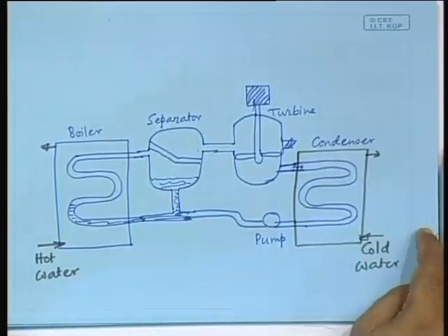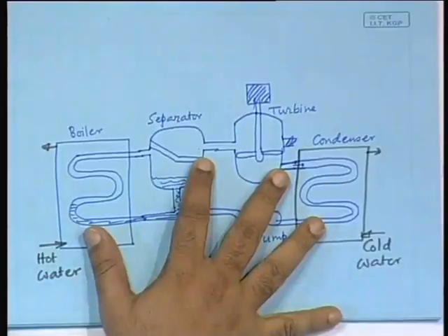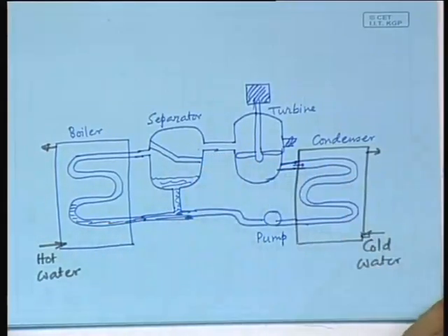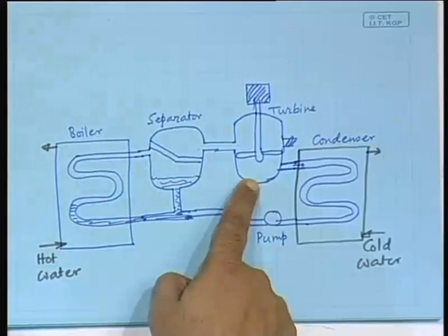So, when we said 1 minus T2 by T1, that efficiency will also go down, right. So, this has a lower ideal Carnot efficiency, but nevertheless this cycle is often preferred mainly because the turbine size is manageable.